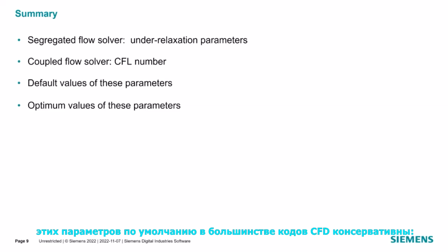Default values of these parameters in most CFD codes are conservative. They work for most flows, but are not optimal for any flow. It is therefore worth trying to use higher values, because that may significantly reduce the computing cost.